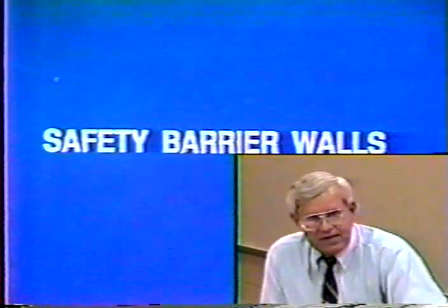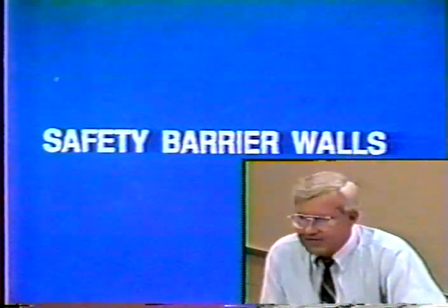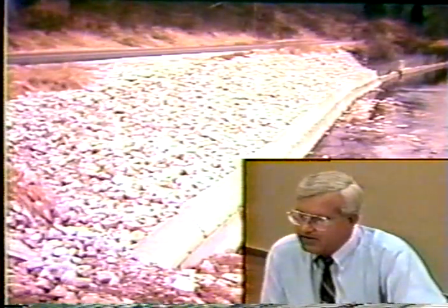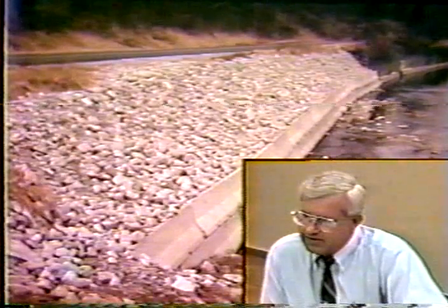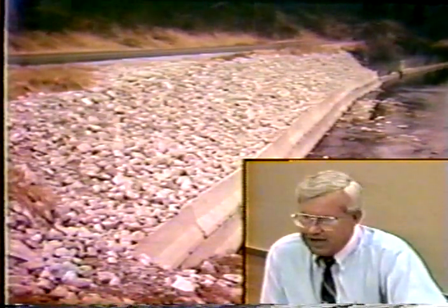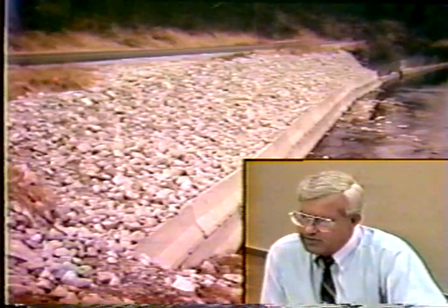Okay, the same thing can be done with old safety barrier walls. You can build the same type of structure. One thing I might mention that he did that you ought to consider when you're using a safety barrier is to try to anchor the wall with an anchor block, just like he did. Here's one application of a safety barrier wall, which works very well.